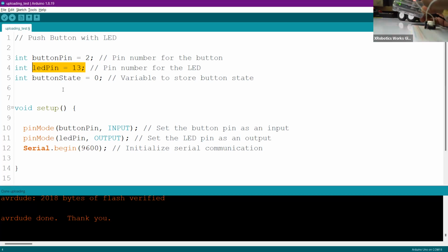I'm connecting one of the wires of the push button to the GND pin of my Arduino. Why GND pin? We always short one of the pins to the GND pin. Either way, you can change the pins to any pins of your choice. It means if you want to give the high value directly to your micro through the push button, then you can directly connect the push button to the positive side of the pin.